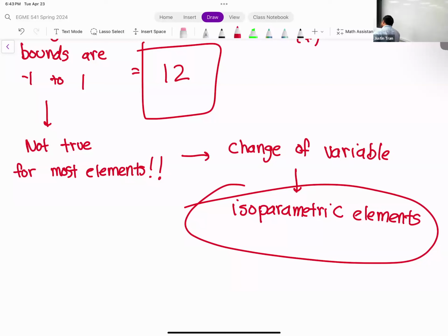So we get the exact solution if the degree of the polynomial is equal to or less than the number of Gauss points in that direction. But what about trig functions, like sine, cosine? Those don't have rules for exactness for Gauss quadrature. Gauss quadrature works over polynomials. You'll get something that's decently close, but it's never going to be truly exact like it is for polynomials. For finite element, trig functions are pretty unusual. So if you have trig functions, there's another numerical integration technique that's better, but the name is escaping me.